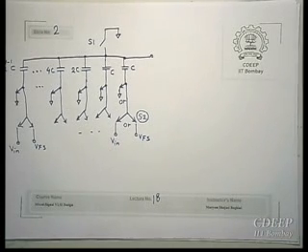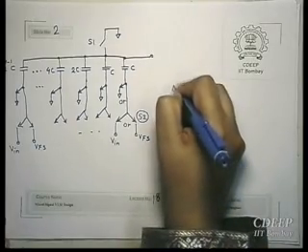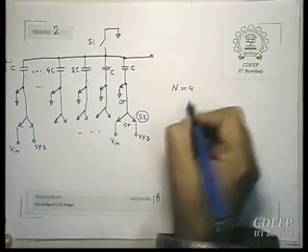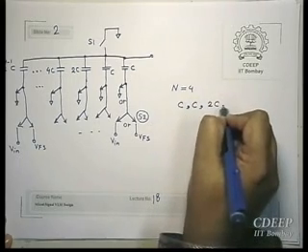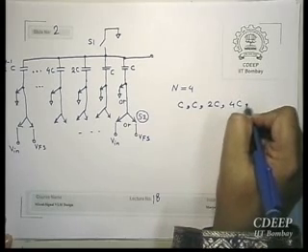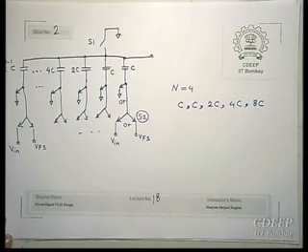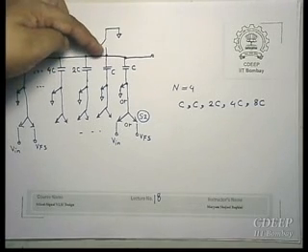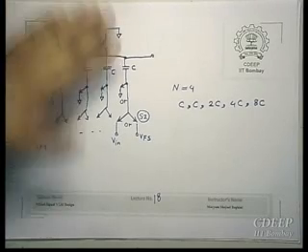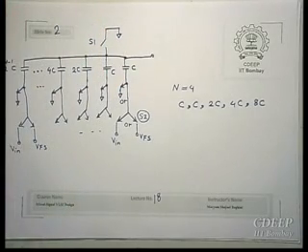Just to make it simple, we go with n equal to 4. Therefore we will have C, 2C, 4C and 8C capacitors. First of all, you will reset all capacitors. Reset is very easy: you connect all top plates and bottom plates to ground, making sure all capacitors have 0 charge.